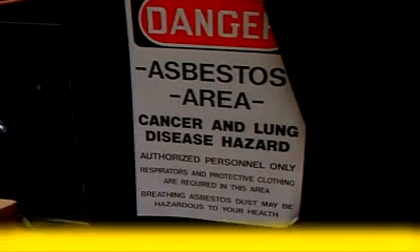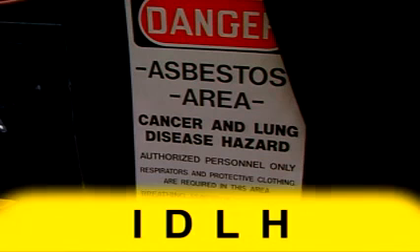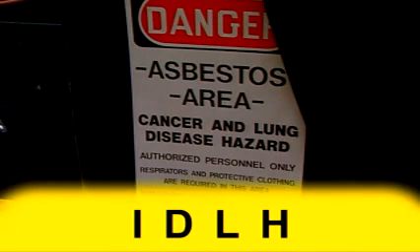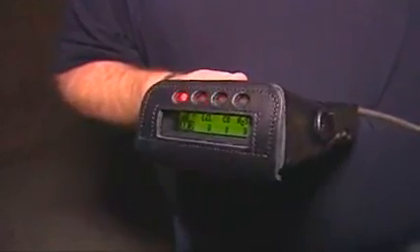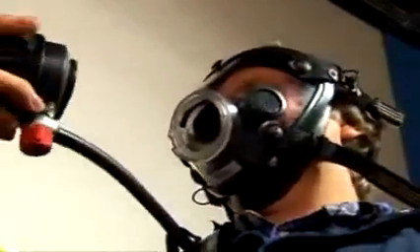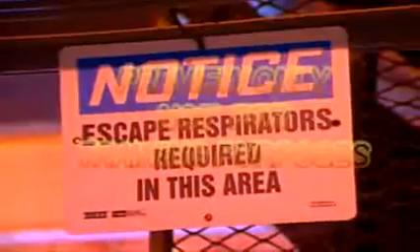Never enter an area designated to be immediately dangerous to life or health, or IDLH, without a proper respirator and training on the atmosphere. All oxygen-deficient atmospheres are considered to be IDLH. Respirators considered for use in an IDLH atmosphere are a full facepiece pressure demand SCBA, certified by NIOSH for a minimum service life of 30 minutes, or a combination full facepiece pressure demand supplied air respirator with auxiliary self-contained air supply. Respirators provided only for escape from IDLH atmospheres should be NIOSH certified for escape from the atmosphere in which they will be used. Other rules may apply to entering an IDLH atmosphere, such as special training, rescue and entry procedures, and additional personnel.